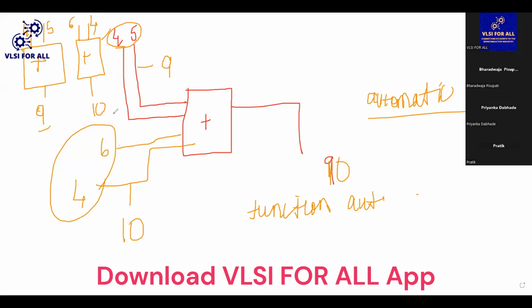So by using automatic, we can save this particular thing. But one problem is, if we are using automatic, we cannot access any internal variables of the function. On every invocation, a new memory will be created. So this is the advantage of the automatic task. So this is the difference between the functions and the tasks with reference to Verilog.